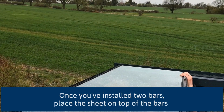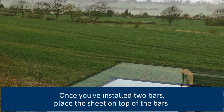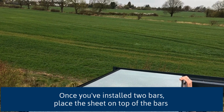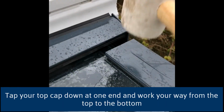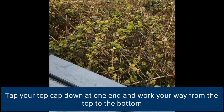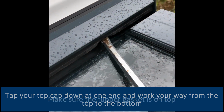Once you've installed 2 bars, you can then place the sheet on top of the bars, ensuring the flipper gasket in the wall plate does not get pushed into the wall plate. Now tap your top cap down at one end, and then work your way from the top all the way to the bottom.